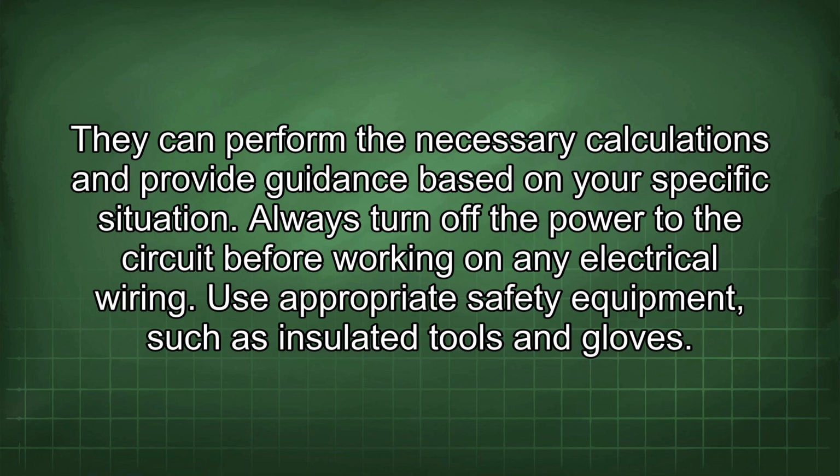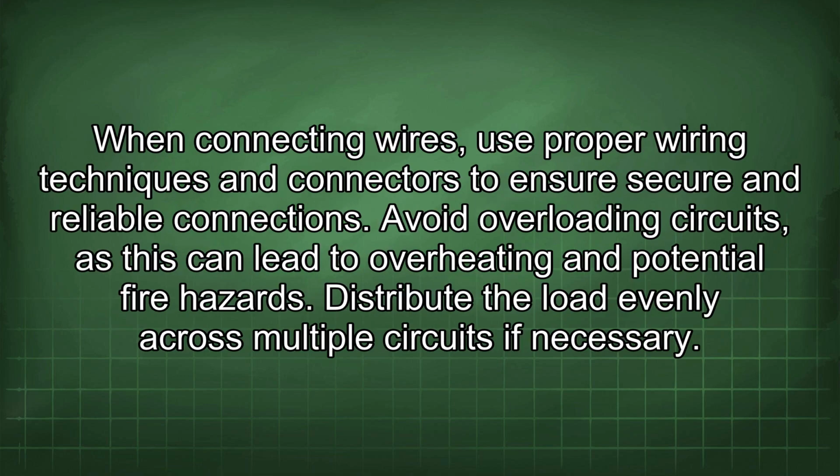Use appropriate safety equipment, such as insulated tools and gloves. When connecting wires, use proper wiring techniques and connectors to ensure secure and reliable connections. Avoid overloading circuits, as this can lead to overheating and potential fire hazards. Distribute the load evenly across multiple circuits if necessary.